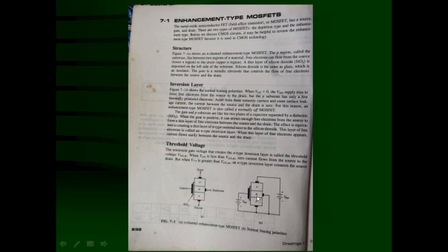But because of the presence of the substrate, normally if VGS is equal to 0, then electrons cannot move from the source to the drain, and this remains open. So it is called a normally open switch between drain and source. Let us see. Figure 7.1b shows the normal biasing polarities. When VGS is equal to 0, the VDD supply tries to force free electrons from the source to the drain, but the P substrate has only few thermally produced electrons.